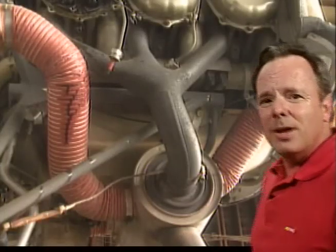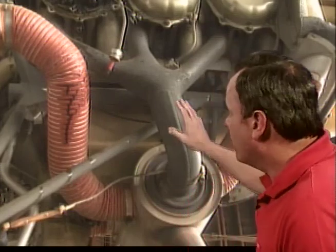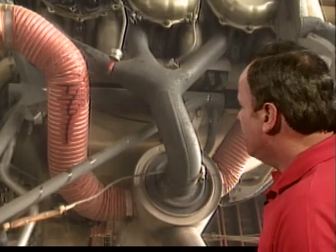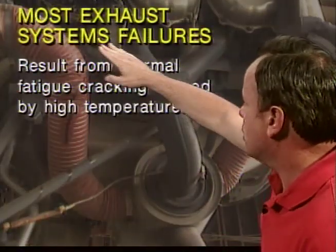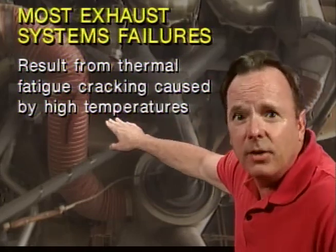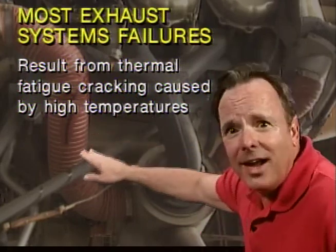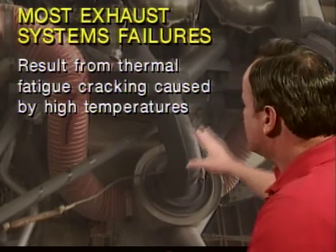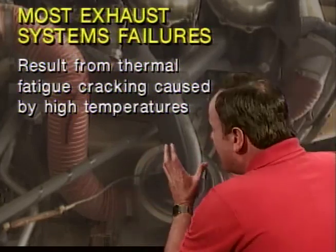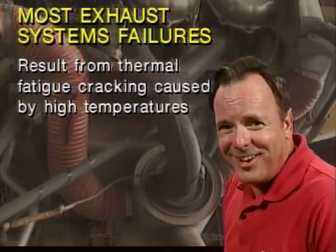Now, you're an old pro, so let me ask you a question that you'll know the answer to from experience. Do you think exhaust systems ever crack and separate and cause leaking? You bet they do, and the FAA refers to these as exhaust system failures. They're going to ask you what causes exhaust system failures. Well, most exhaust system failures result from thermal fatigue cracking in areas of stress concentration, and this condition is usually caused by high temperatures at which the exhaust system operates. So what you need to know for the test is, son of a gun, these things get hot. They have cracking, and that's called exhaust system failures from thermal fatigue.